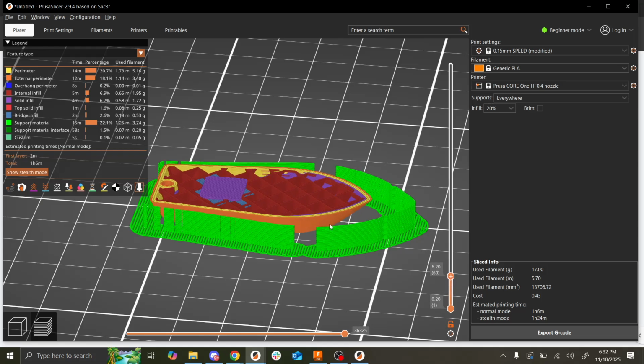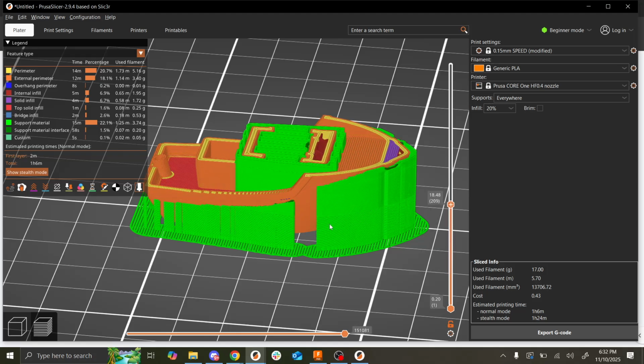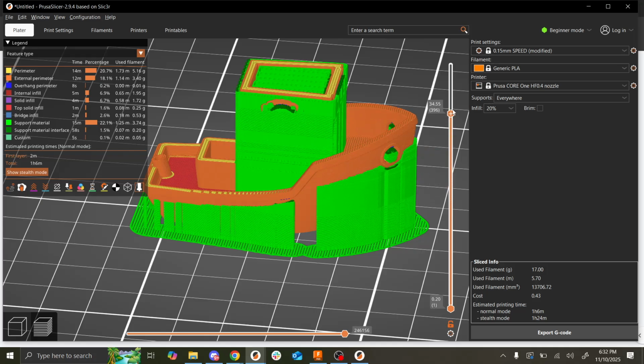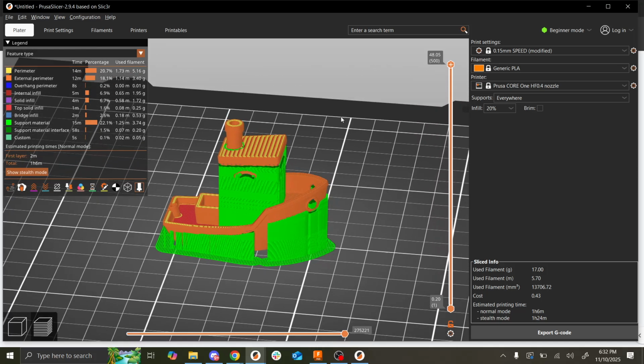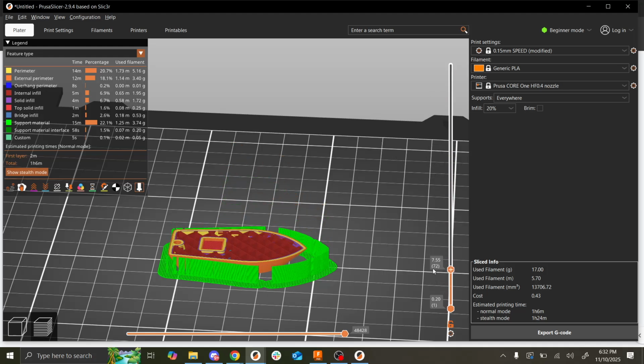There's the infill. You see it's nice and hollow, and it'll just do that many, many times until you get your part. So over here, you can see that there's a total of 500 layers that this printer has to go through to make your model. And it'll do that for every single part you make. So you can see this is kind of how the slicer works.